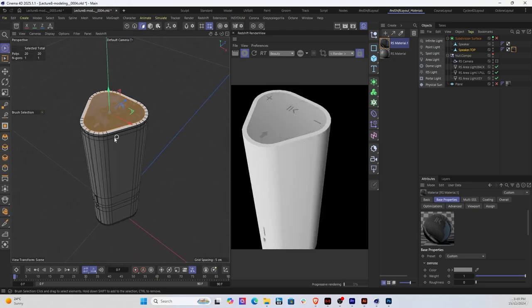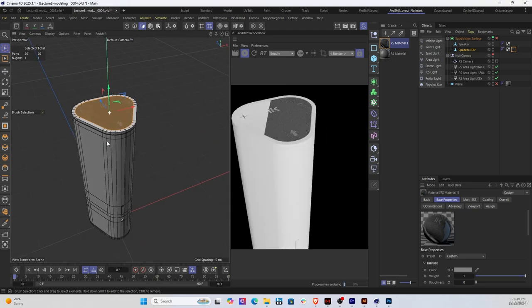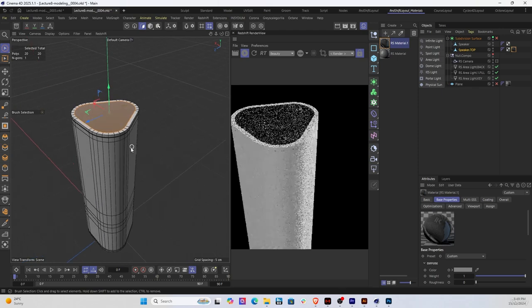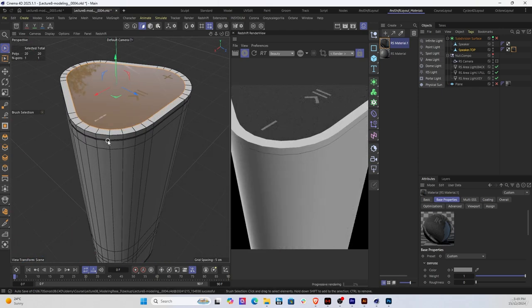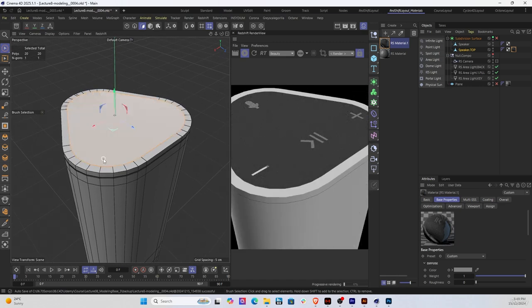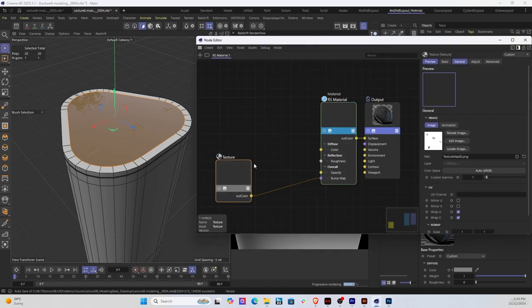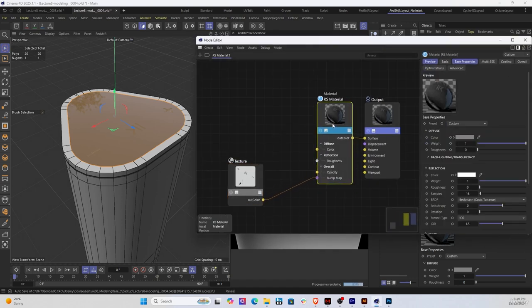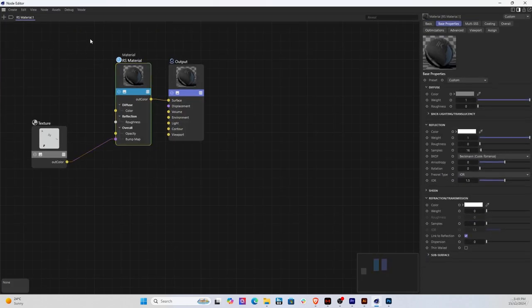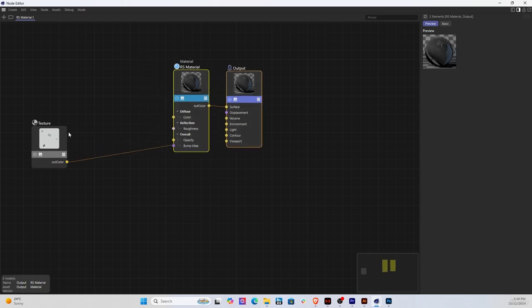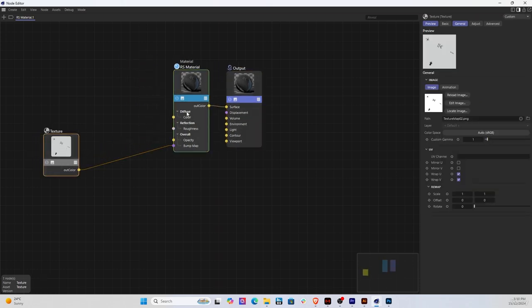The reason why we're getting these lines is because of the reflections of the material that we've applied here, which isn't right. So these are the textures that we're getting, right? So what we should do is go back to the material, and from here we need to also ensure that we are using a bump map, not feeding just the texture into the bump map of the material, but we need to convert this texture into a bump map.